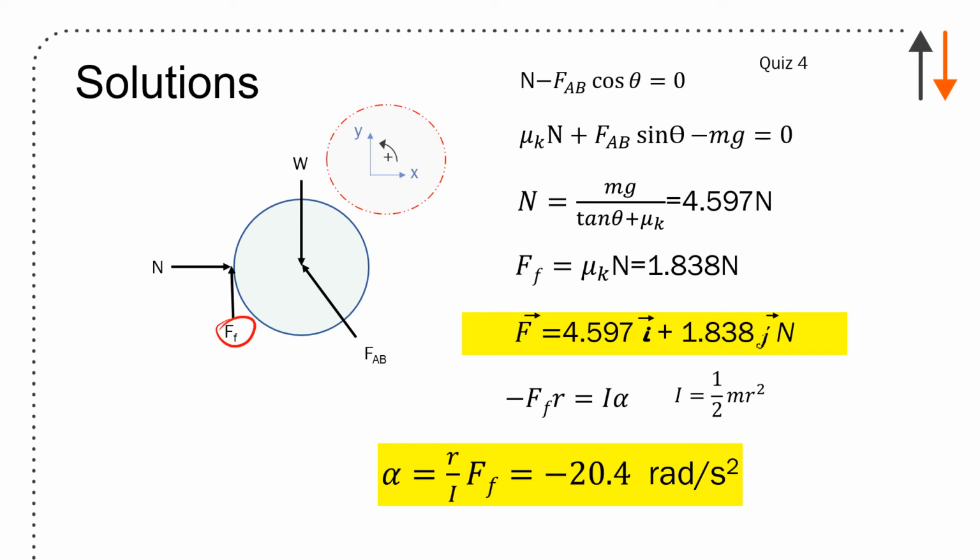Often the problem was this point right here, where it was done in a way that didn't seem intuitive. You may have some difficulty seeing how this belt is doing this. It's fine. Just get used to writing the friction down, so it allows you to write it as a positive value: N minus F_AB cos θ in the x direction. And over here, friction force, you have the component of the belt force and the weight acting in the y direction. Substitute in all the terms and calculate everything.